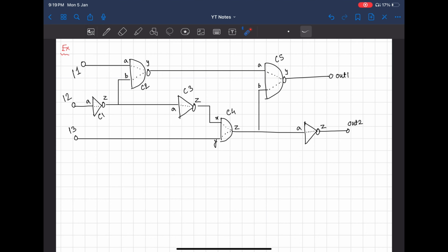I have to draw the timing graph, and then I will specify some timing constraints. I will assume some timing constraint at the input when we cover the arrival time, and the same at the output node when we cover the required time. So let's visualize it in the timing graph.